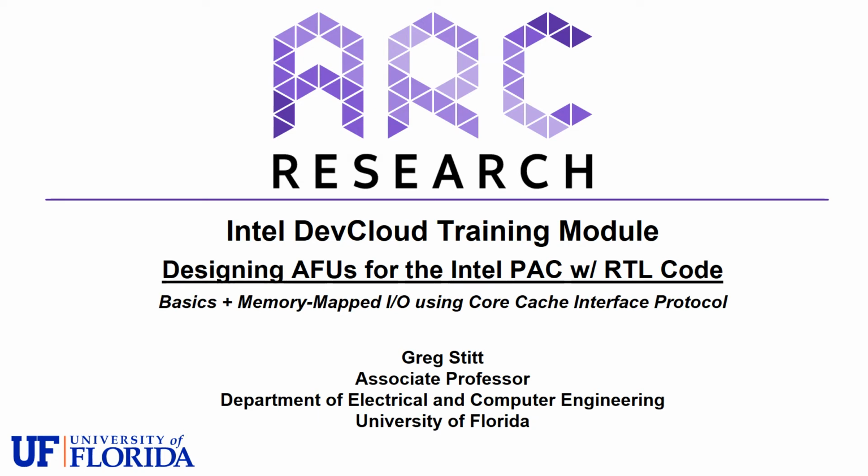In this video, I will be continuing with the training modules for the Intel Platform Acceleration Card using the Intel Dev Cloud. This will be the first video on how to design AFUs using register transfer level code. And in this video, I will cover the basics of AFUs and then look into how you can perform memory mapped I/O over CCI-P or the Core Cache Interface Protocol.